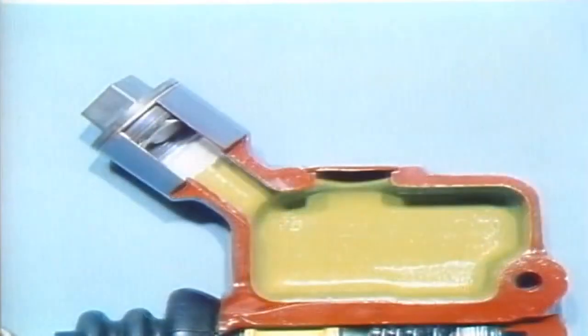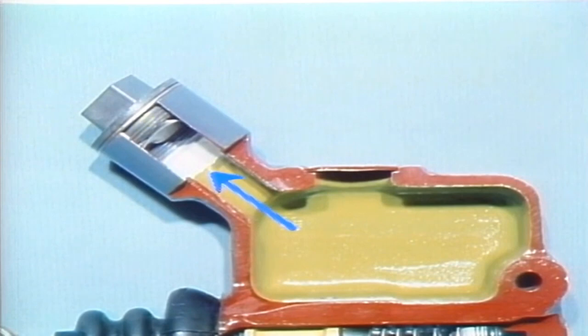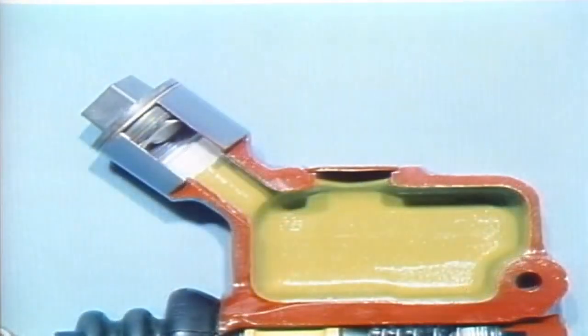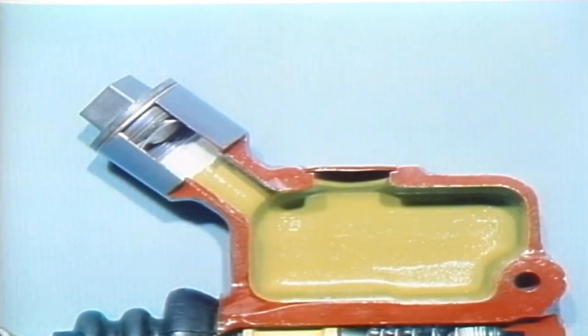The reservoir contains a supply of brake fluid. It's important to leave some space above the brake fluid to allow for expansion. Brake fluid must not be allowed to drain out of the reservoir completely, because it will let air into the brake lines, and we'll see what effect that has later. Your manual will tell you what the proper level is. Keep it there at all times, and you won't get yourself or the users of the vehicle in trouble. One thing more about brake fluid: it absorbs water, which could cause serious problems all throughout the brake system. So keep the reservoir tightly covered at all times.